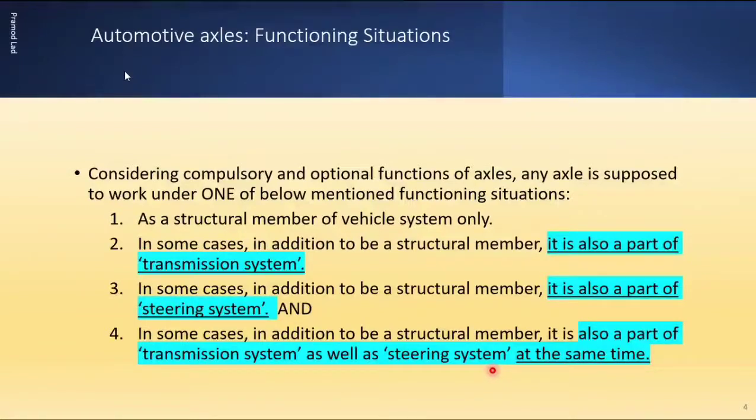First is as a structural member of the vehicle system only. There are some axles which will be performing their duty as a structural member only and nothing else. Second is that in some cases, in addition to being a structural member, the axle assembly is also a part of the transmission system. That is, it contains the differential gearbox and it gives the speed difference for left side and right side wheels.